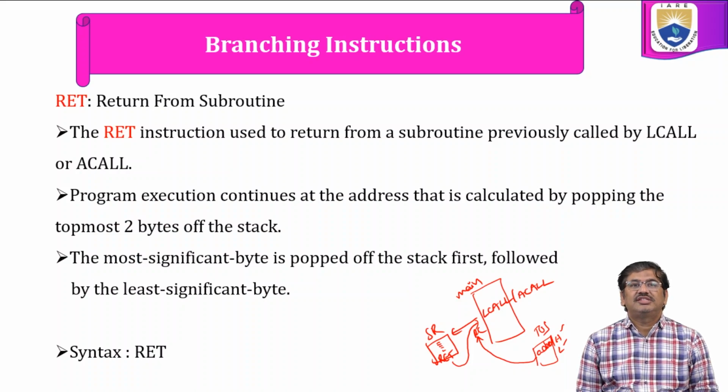The syntax of the instruction is RET, which will not have any operand. It is simply RET, indicating return from a subroutine. The RET instruction should always be the last instruction in a subroutine. Suppose in a subroutine we have not written the RET instruction, what will happen? The program, from the location specified for the subroutine until a RET is encountered, the microcontroller will treat as the entire program corresponding to the subroutine we called. So the RET instruction we compulsorily have to write as the last instruction in the subroutine.